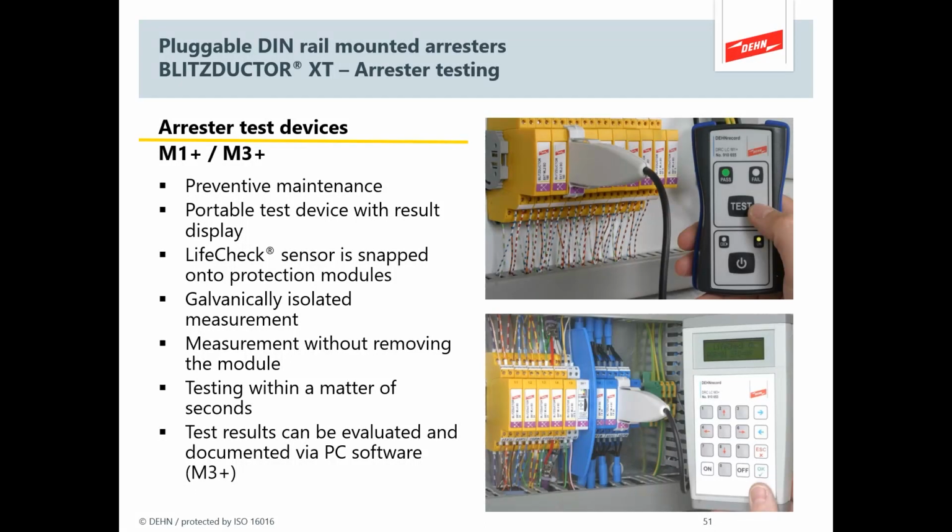First of all, we've got a handheld tester, and there are a couple of models. There's the bog standard one, which you can just hold over the SPD itself. That's with SPDs with this feature. It's called Life Check. And you hit the test button and it either gives you, yep, that one's okay, or it isn't, because you can't tell by looking at the SPD itself. Another version of this is, again, a push button arrangement, and this time you save the results in the actual device itself, where you can download them via an interfacing cable. So you can have a basic tester or a more bells and whistles version.